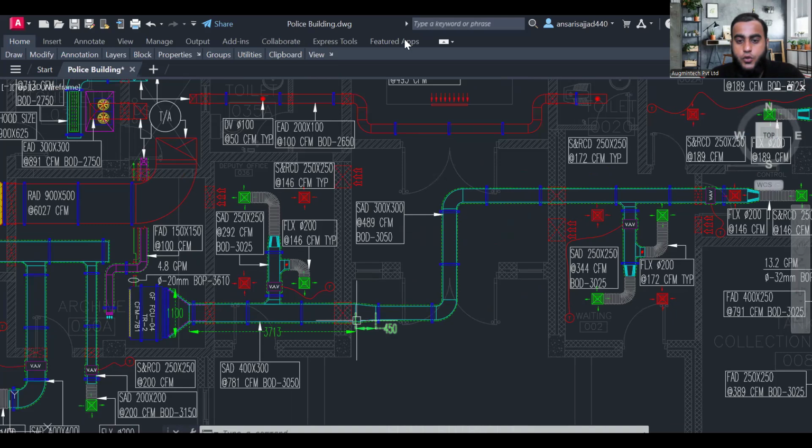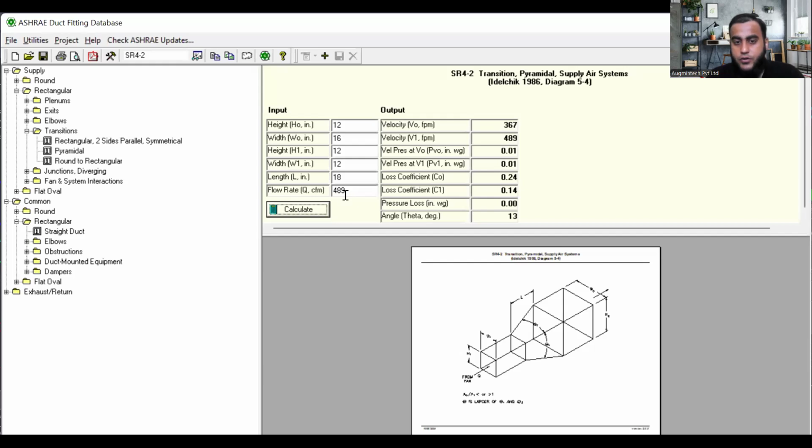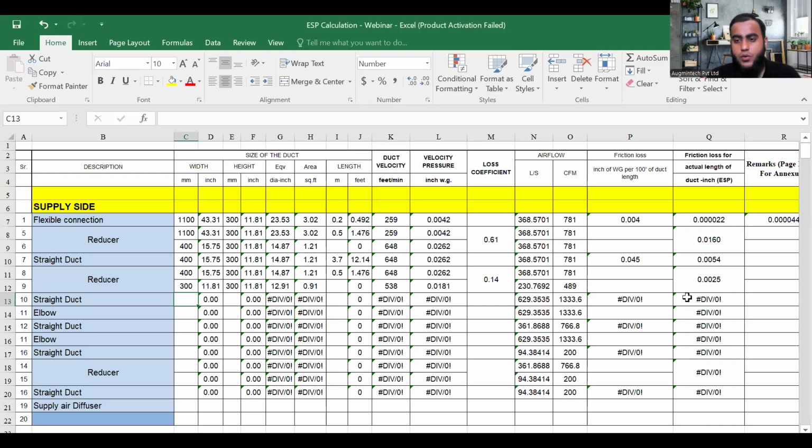So simply, you can go for manual calculation or otherwise software. In software, when you enter all these values, the flow value, remember, after reducing, whatever you are getting, it is coming 0.00 something. But in software, you will only get the value after the decimal up to 2 places. So better is to go manually here, because a very low friction loss is coming. In our case, it is C into PV, loss coefficient into velocity pressure. As per that, 0.025. Clear?